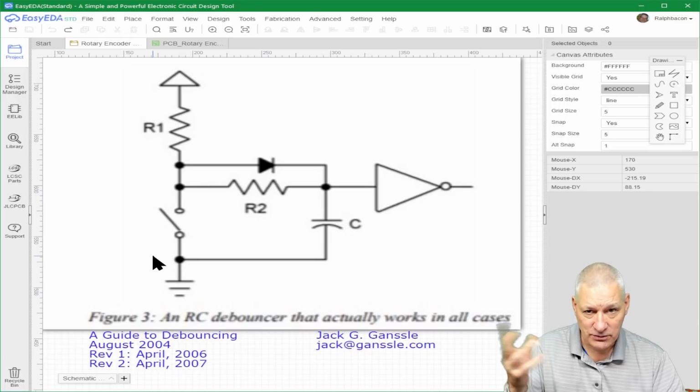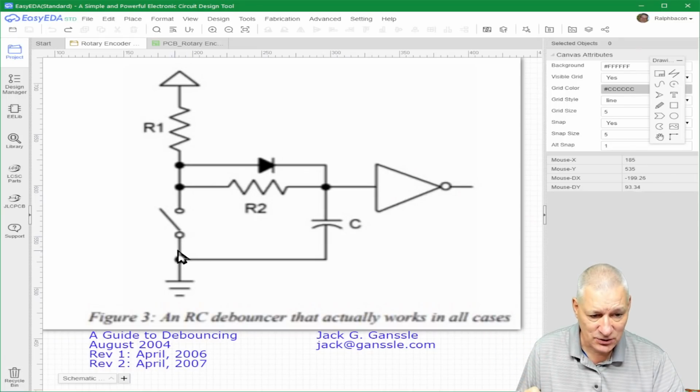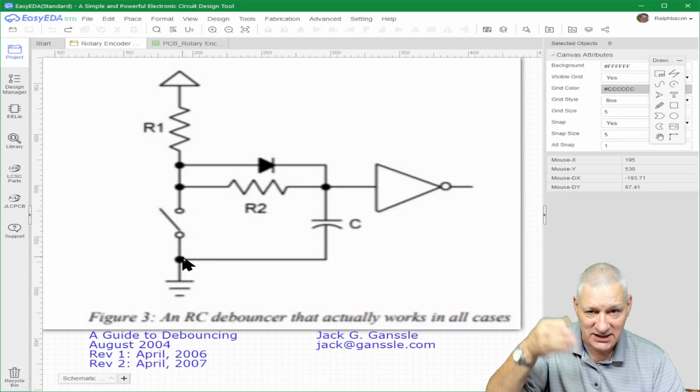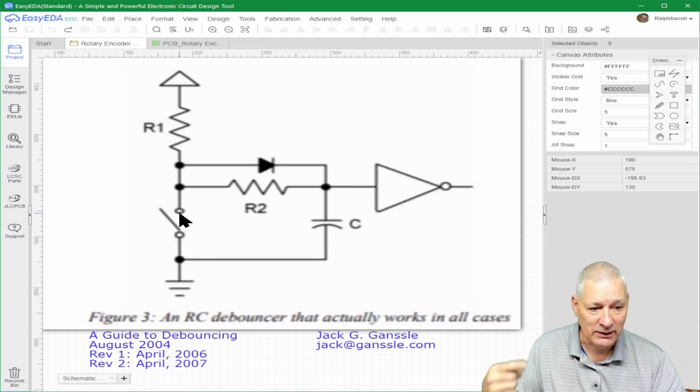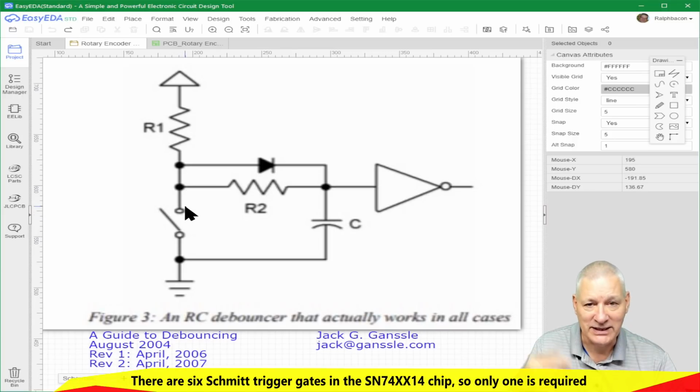Well, the switch, the rotary encoder switch, is connected between ground on one pin, say pin, well, it's the center pin actually, and then you've got pin A here, but what do you do with pin B? Well, you have an identical circuit, and pin B is connected to the same place, but in a different circuit, okay? So what's happening is here, this is VCC up here.